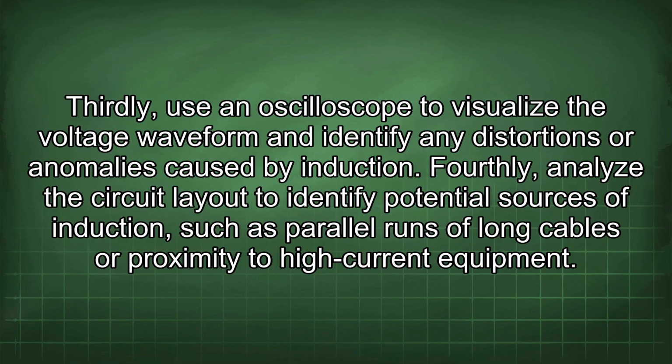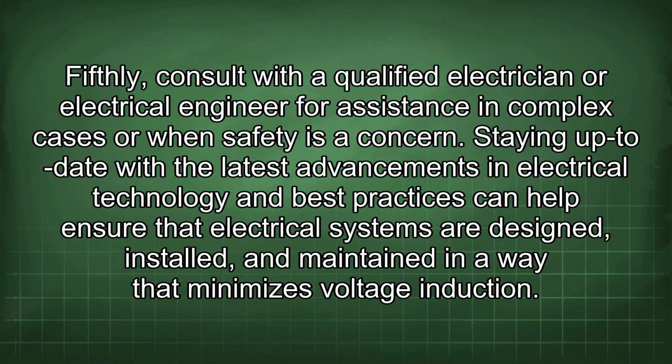Fourthly, analyze the circuit layout to identify potential sources of induction, such as parallel runs of long cables or proximity to high current equipment. Fifthly, consult with a qualified electrician or electrical engineer for assistance in complex cases or when safety is a concern. Staying up to date with the latest advancements in electrical technology and best practices can help ensure that electrical systems are designed, installed, and maintained in a way that minimizes voltage induction.